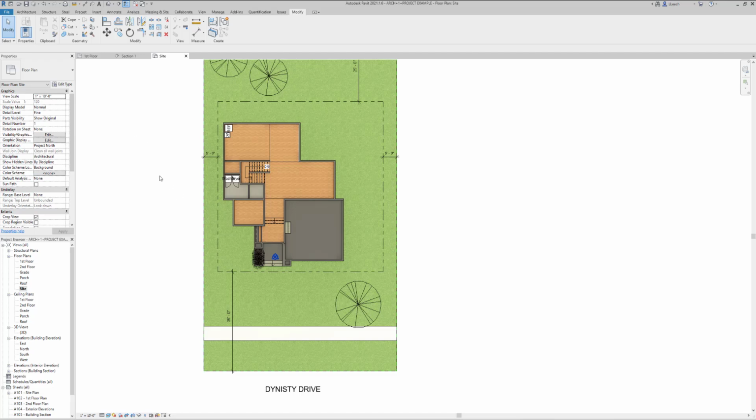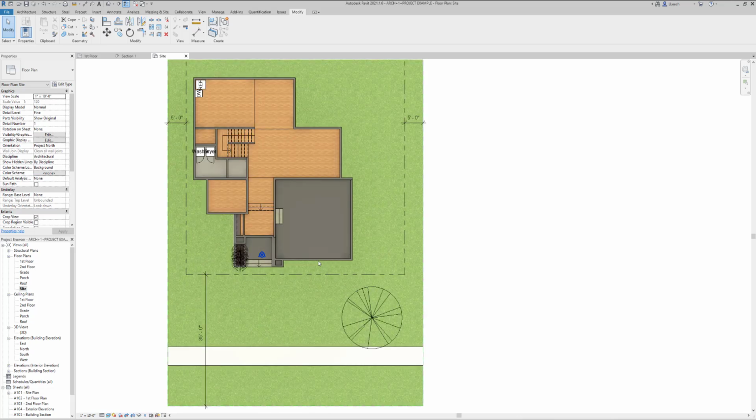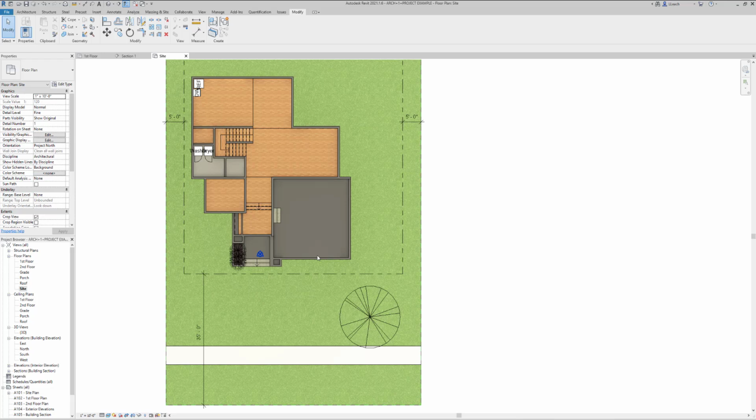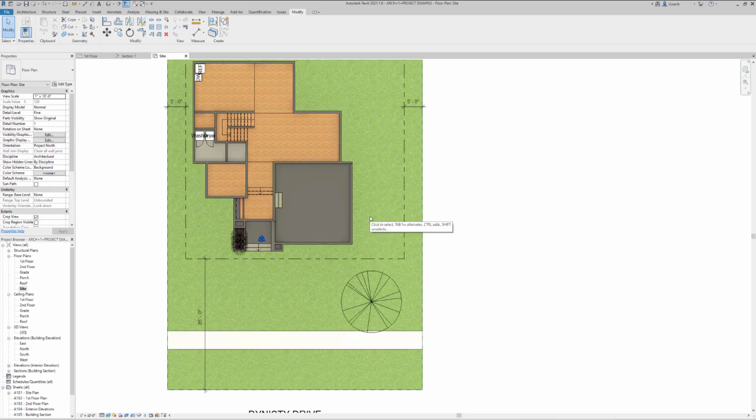All right, so the next thing I want to do is, you see how I have my sidewalk here? I'm going to cut a path to where I can draw a driveway, maybe even a sidewalk to get to my porch. One thing that might help is I'm going to draw my driveway where my garage door is, but right now my cut plane is like 200 feet in the air. So temporarily, I want to know where this garage door is located. The easy way to get to your cut plane is to type in VR.